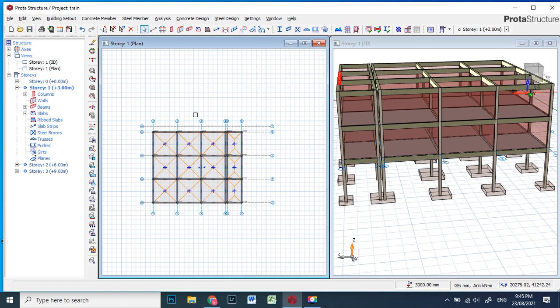The first test you need to do is the pile integrity test, and the other test you need to do is the pile loading test. With these two test results, you can tell if your pile fails or not. But the first thing you need is your soil test report showing the capacity of your pile. Let's assume your pile capacity can take 1,000 kilonewton. From your design, if your pile is taking more than that, it has failed.